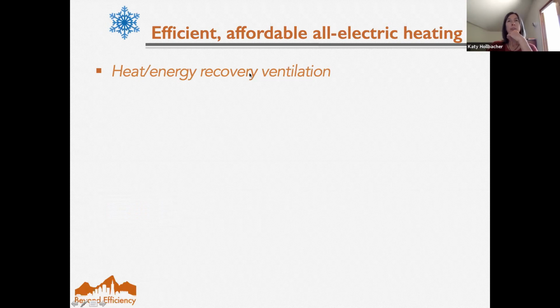So here's a concept that is an interesting approach, what I would call, again, efficient and affordable all electric heating. It's more expensive than doing all electric resistance, but less expensive than doing only a heat pump or a primarily heat pump based system in a building. This presumes that heat recovery ventilation is a given, because that will serve to reduce the heating demand that needs to be made up for with your space heating system.